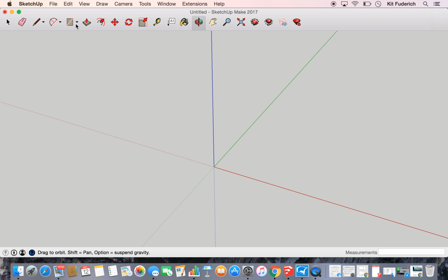I'm then going to go ahead and look at the top icon that's shaped like a square, a rectangle in fact. Select it, click the origin once, and move away from it. And we know that the succulent plant's dimension is 48 millimeters by 48. So I'm going to type in 48 on my keyboard, comma 48, and then enter. Notice how in the bottom right corner the dimensions also say 48, comma 48.